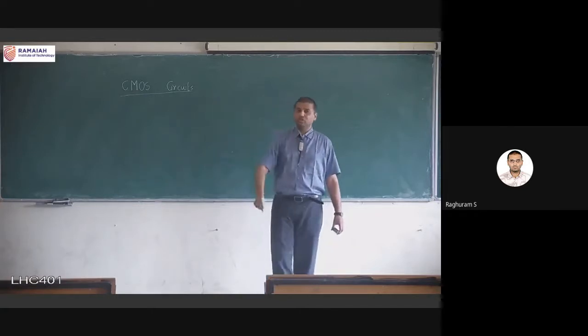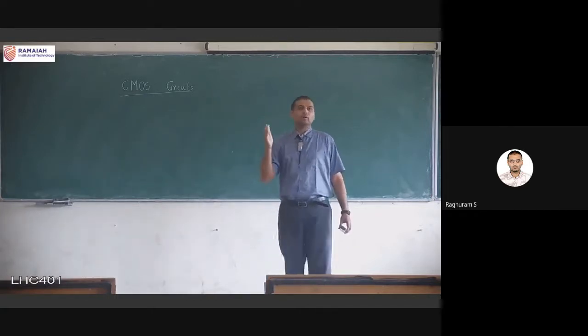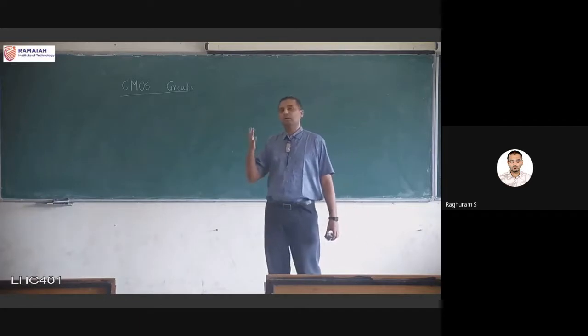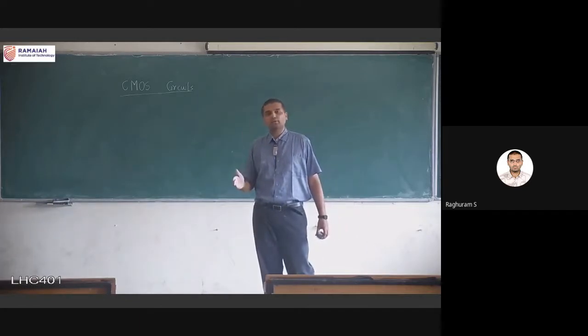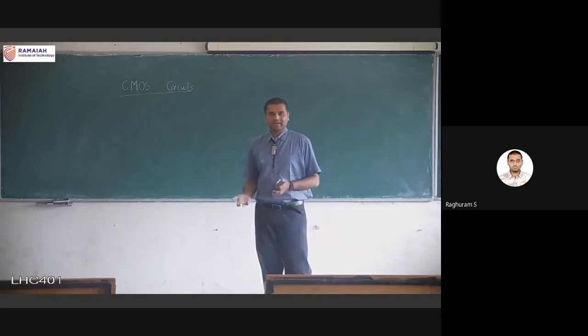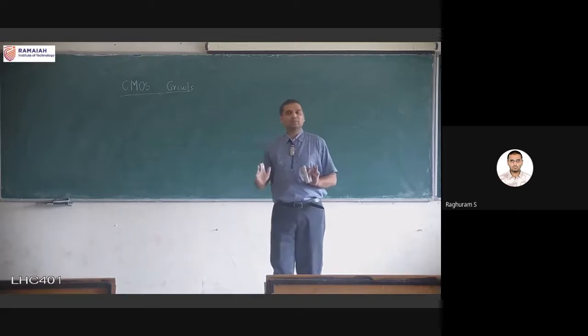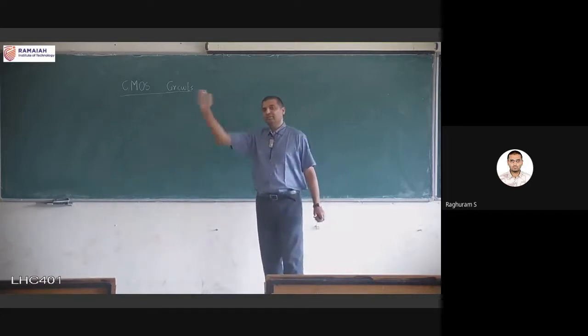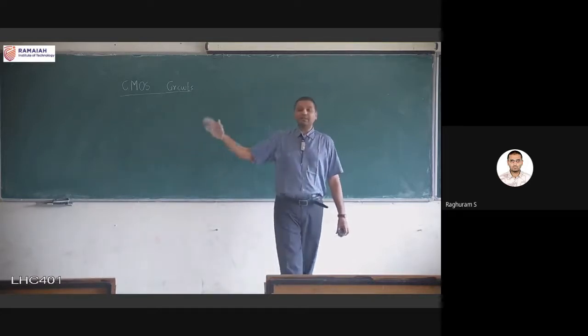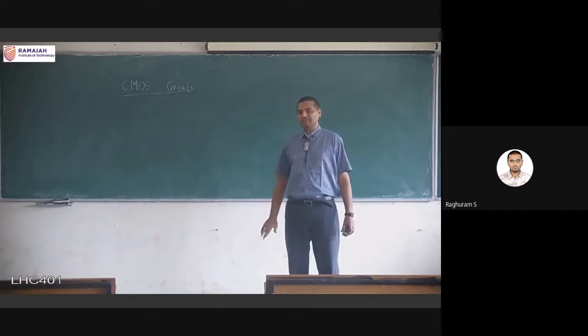And I also mentioned this in the slide, very important. Do not get confused between terminologies. If I say circuit, it means that it has to be at the transistor level. It cannot be at the gate level. Don't draw the old diagrams you have for AND gate, NAND gate, etc. That is not what is meant by circuit. That is a logic level schematic. This is a circuit level schematic.